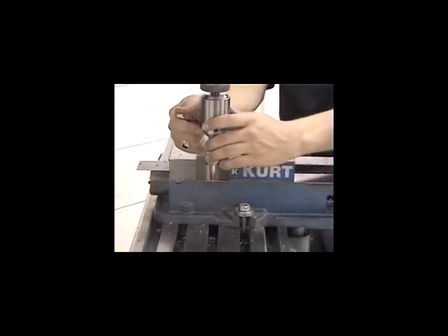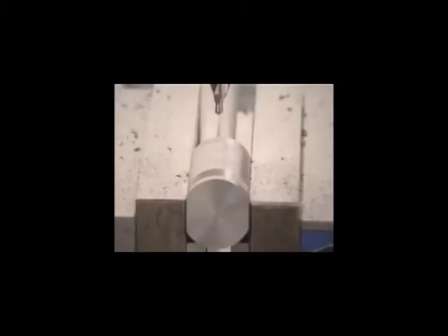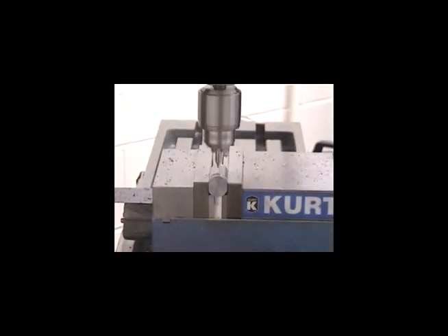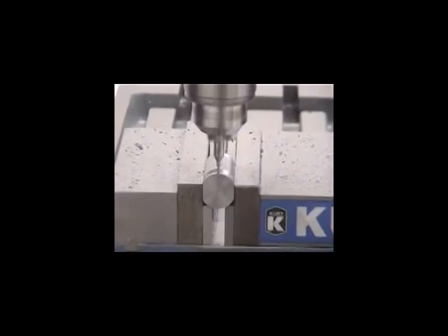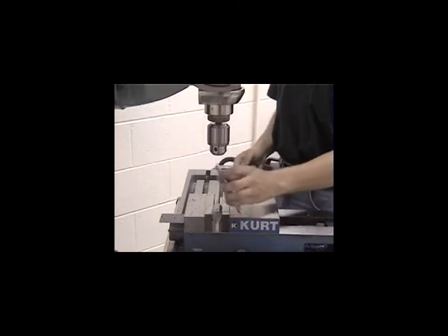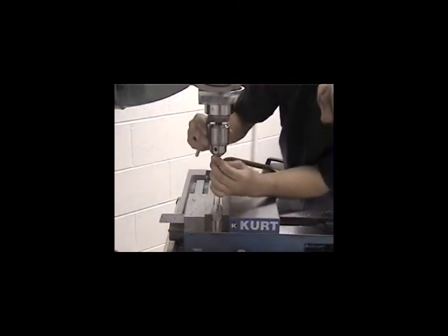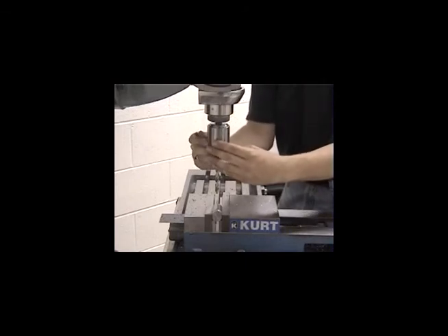It will not flex when the hole is started, so the position of the hole is quite exact. The starter bit is used to drill a pilot hole, which is a short hole used to guide a full-size drill bit into the piece. You advance the bit with the quill downfeed lever. After the pilot hole is drilled, you put the drill bit corresponding to the desired hole size in the chuck. You then advance the bit with the quill downfeed lever.